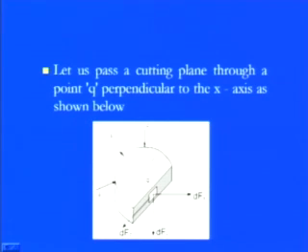You have seen in this figure that all the forces are being applied to the object, and at this particular point we have chosen a small segment whose area is delta A. Because we have chosen three different directions, in the x direction the force dFx is perpendicular to the cutting plane, as we have seen in this figure. But the other two forces, dFy and dFz, are not perpendicular to this concerned axis, the x-axis; they are parallel to the cutting plane.